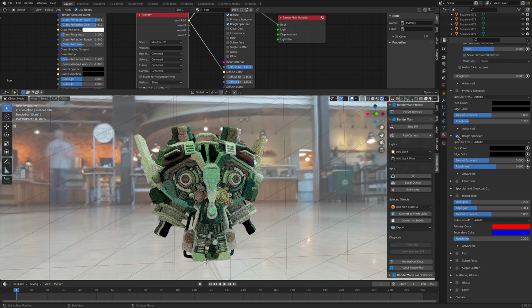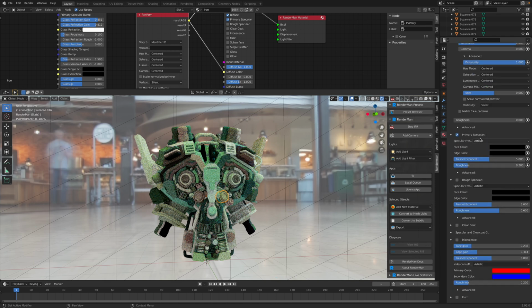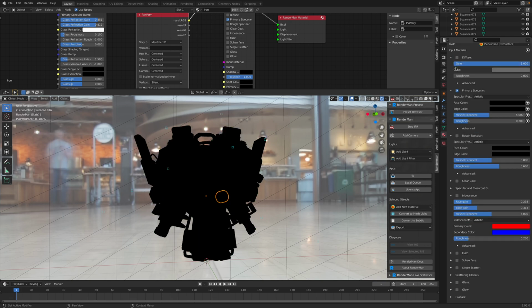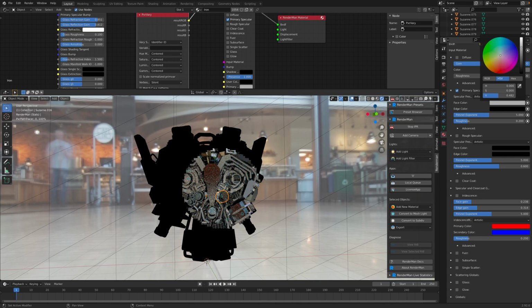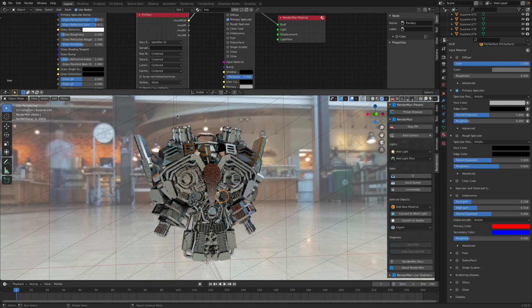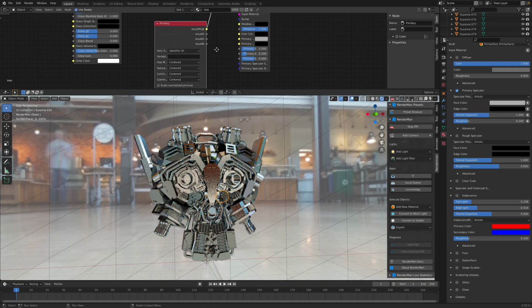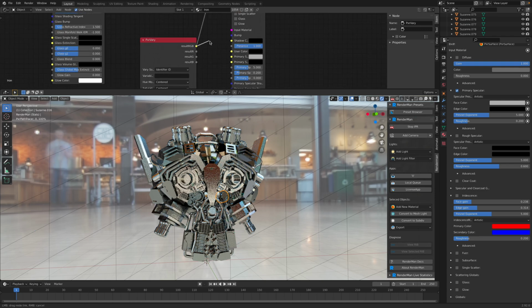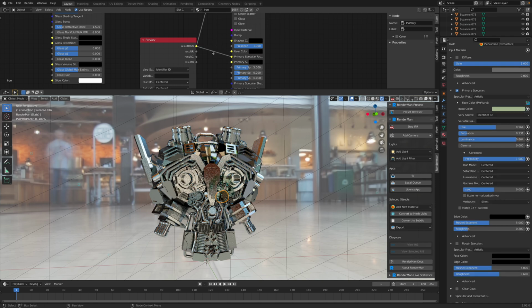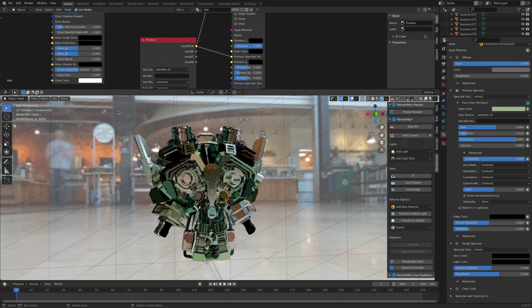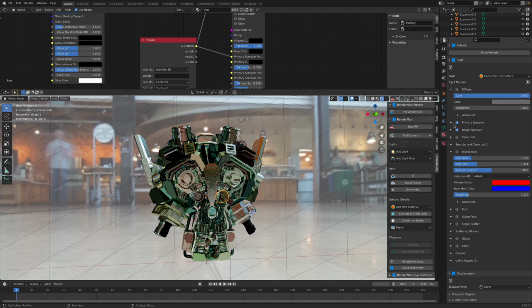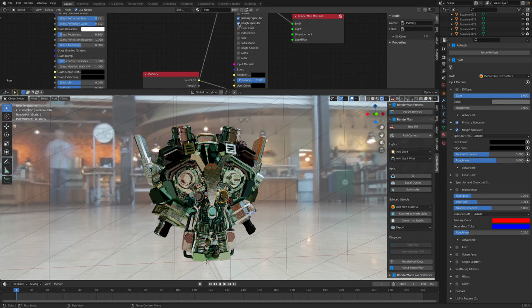So rough specular, if I started to add specularity, I can actually turn off things like diffuse. If I'm turning off the diffuse, now I'm just working with the specular. This is what I get by default, and all the beautiful reflection is coming from this Atrium, Pixar Atrium. We haven't used the PxrVary yet. I can plug this into this guy, like that. Again, another different look. And on top of this is primary specular. So get used to collapsing and uncollapsing this thing, and also clicking on and off here.